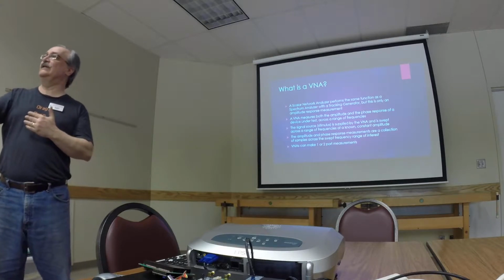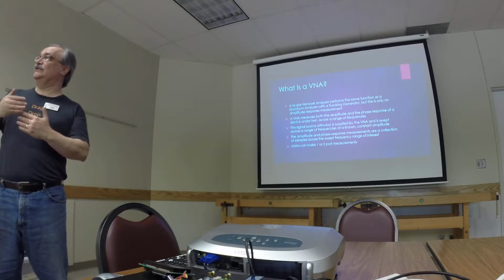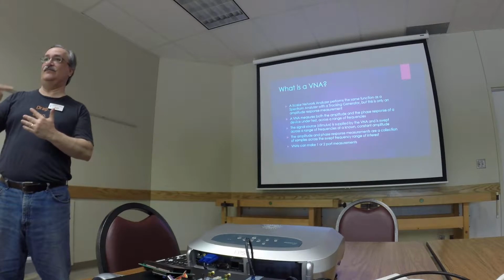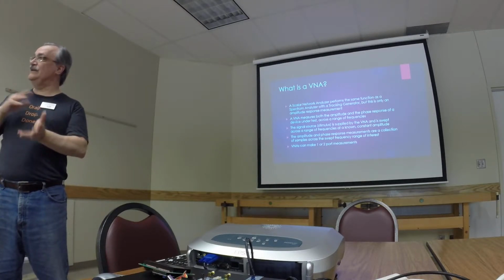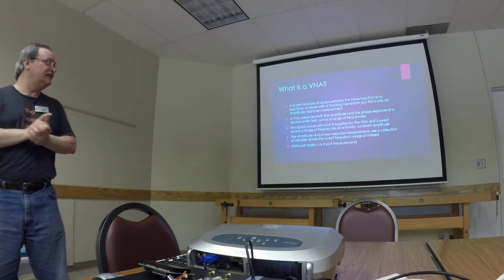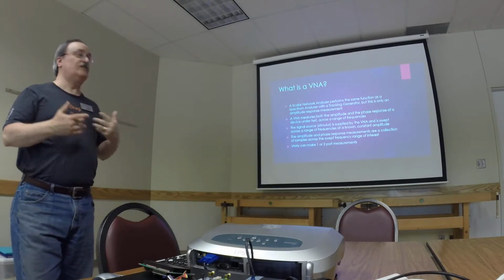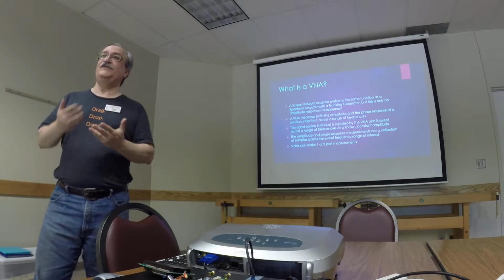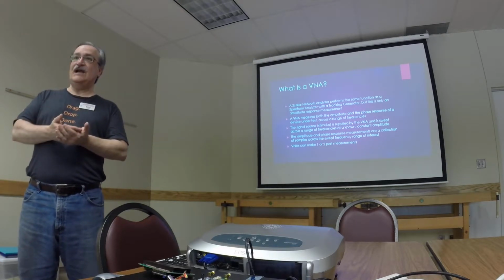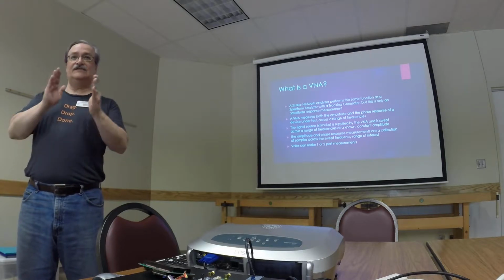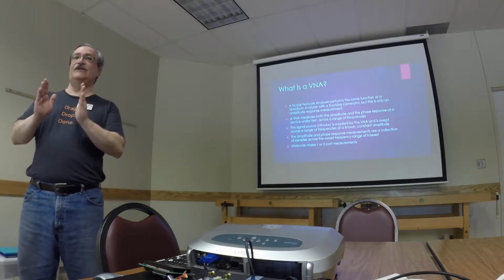They use a directional coupler to see the power reflected back, and then you can arrive at voltage standing wave ratio, among other things. It's the same in effect if you have a spectrum analyzer with a tracking generator that allows you to set a stop frequency range.